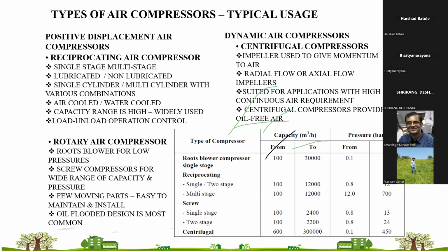In your HVAC, you will have the majority of your requirements in TR, ton of refrigeration. Let's say 2.2 TR is required. For that particular 2 TR delivery, removal of the heat of 2 TR from your particular cubicle, we'll be requiring certain airflow, say 1200, 1400 CFM.